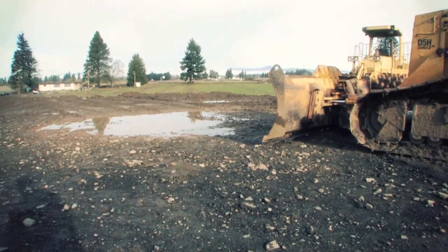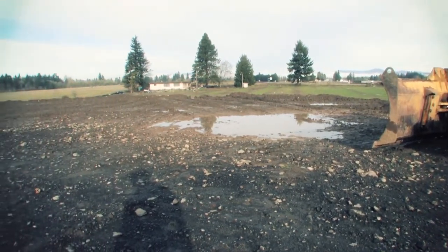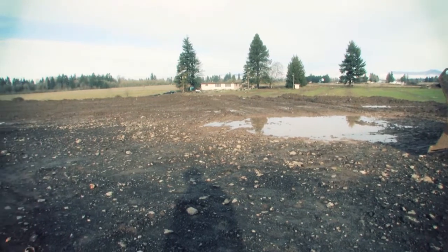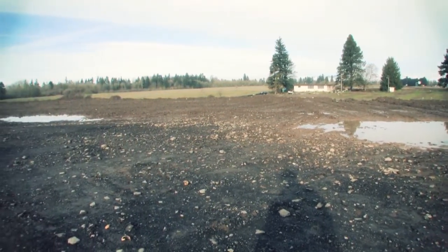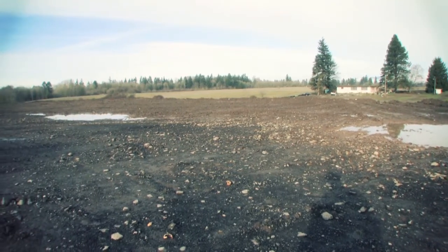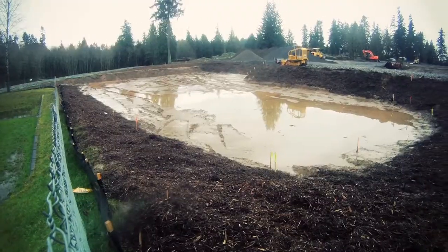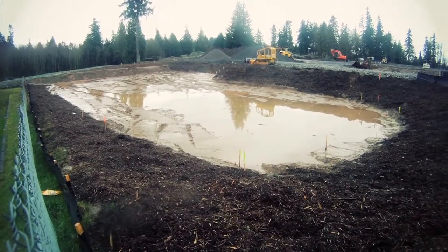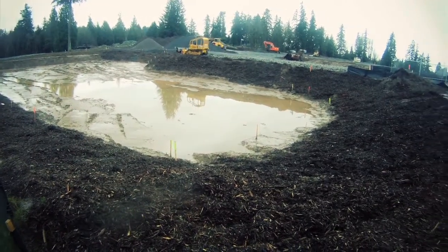Construction of bioretention areas is best suited to sites where grading or excavation will occur in any case so that the bioretention area can be readily incorporated into the site plan without further environmental damage. Bioretention should be used in stabilized drainage areas to minimize sediment loading in the treatment area.